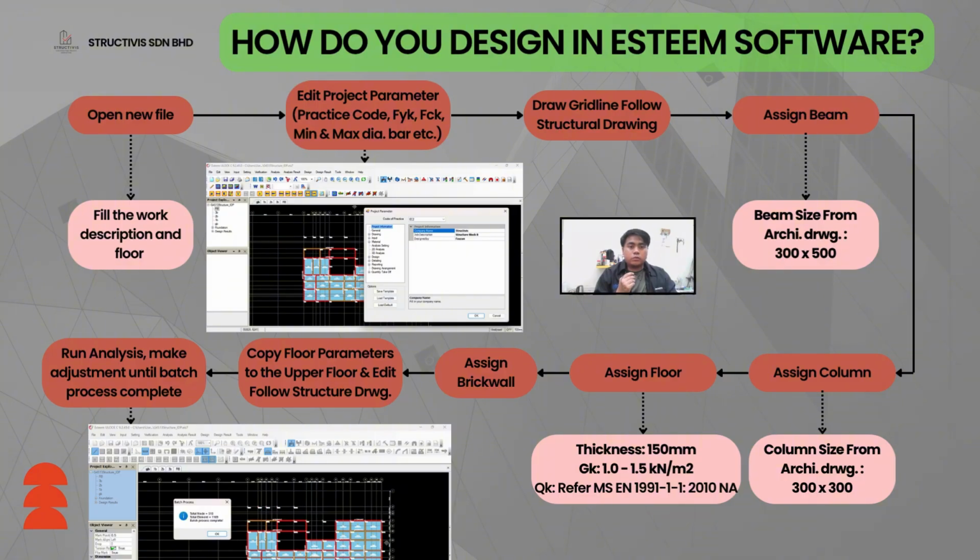with the value GK varying in the range of 1 to 1.5 kilonewton per meter square, and for the value of QK, we are referring to the Malaysian Standard in Eurocode 1 National Annex. After that, we assign the brick wall and we copy the floor parameter to the upper floor and edit following the structural drawing. And lastly, we run the analysis and make some adjustment until the batch process is completed.